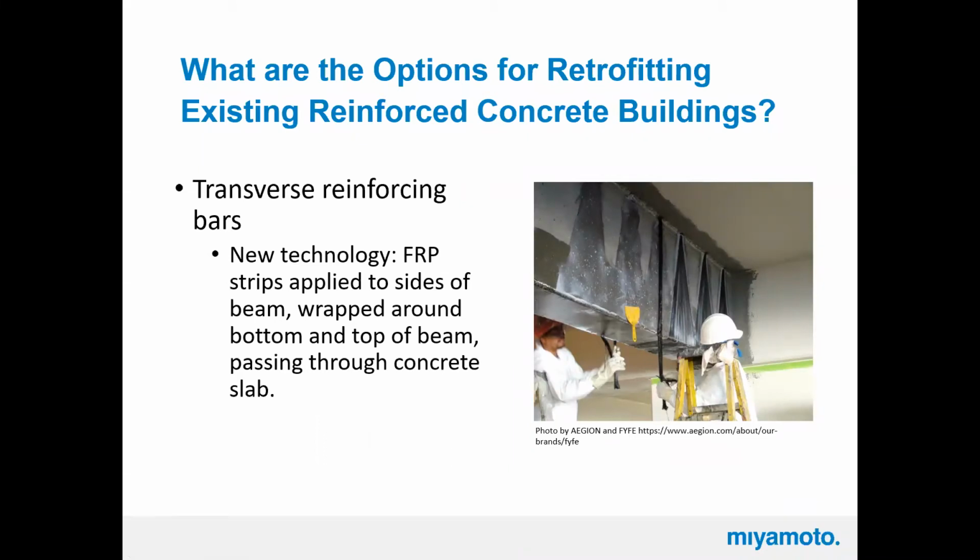You can't really see, there's not really a good picture of those anchors dialed into the slab of the FRP. It's kind of pretty cool, actually. But you wrap the top and the bottom, it adds a lot of shear strength, and it also adds confinement. So it's a very good technology. I like it a lot, especially when you don't have headroom issues. This looks like a parking structure beam to me. I could be wrong, but it looks like it's shaped like one.